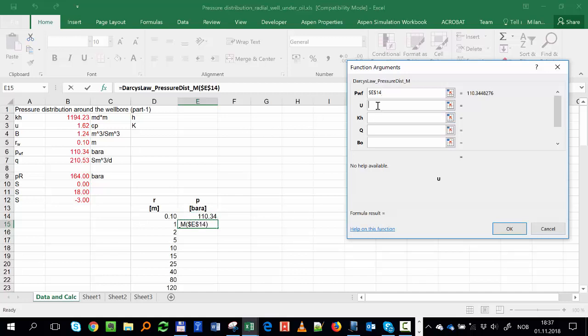This mu is not velocity, don't be confused. That's viscosity, which I have here, 162. Remember, water is 1 centipoise. So 162 is like 50% more viscous than water. It's a bit less viscous than car oil, more or less. Then I block it also. The viscosity will be the same. Remember we said it doesn't change, that's why we could take it out of the integral.